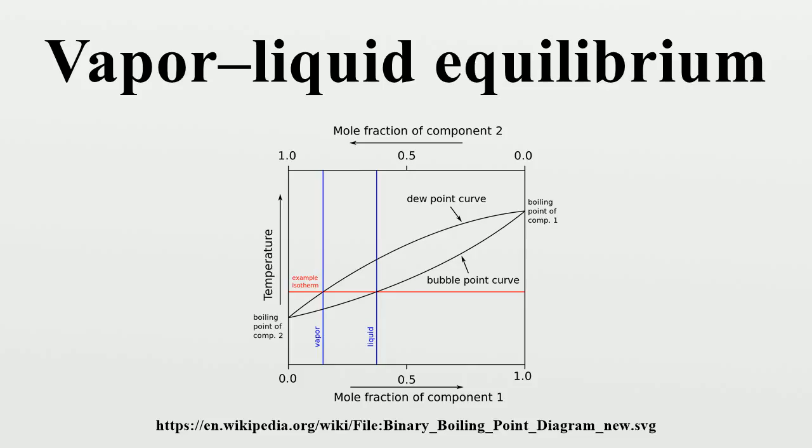At boiling temperatures, if Raoult's law applies, a number of the preceding equations in this section can be combined to give the following expressions for vapor mole fractions as a function of liquid mole fractions and temperature. y1 equals x1 P01(T) over PTOT, y2 equals x2 P02(T) over PTOT, etc. Once the bubble point T's as a function of liquid composition in terms of mole fractions have been determined, these values can be inserted into the above equations to obtain corresponding vapor compositions in terms of mole fractions.